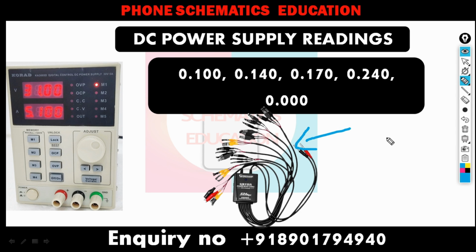When you connect your battery to the phone and turn it on, if your phone is okay, then it turns on. But with the boot cable, it does not turn on. It shows these types of readings. Sometimes it goes to 100 and then goes back to zero. Sometimes it boots up 140, 170, sometimes 140 and back to zero.